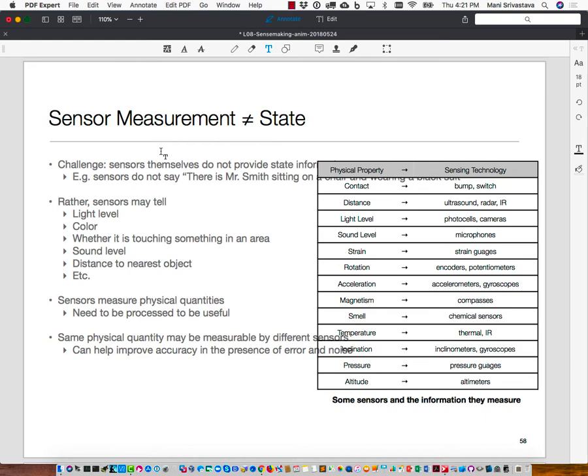From that, it can get the slope, so it can see the power consumption, how much power was being consumed. Then it turns out that on phones, a big part of power consumption really is the cellular radio, because we talked about it earlier also, long distance radios consume a lot of power. For the cellular radio, the power they consume is a function of distance. We again saw that when we talked about the radio, d to the power n.